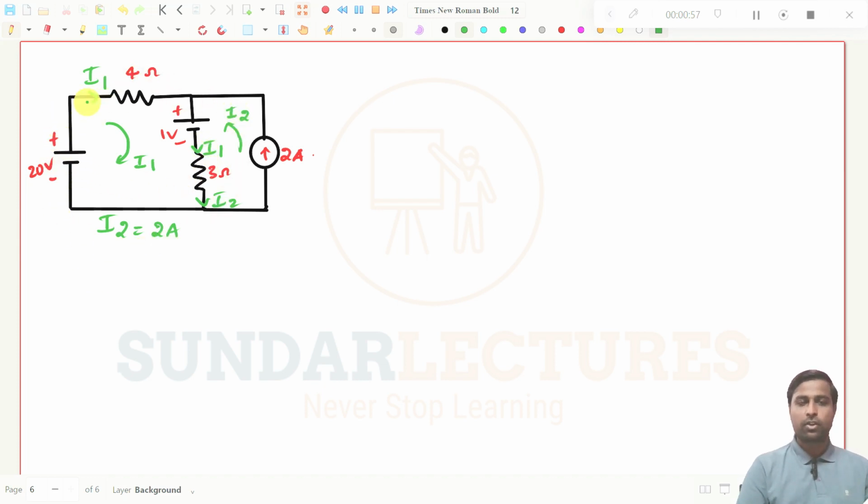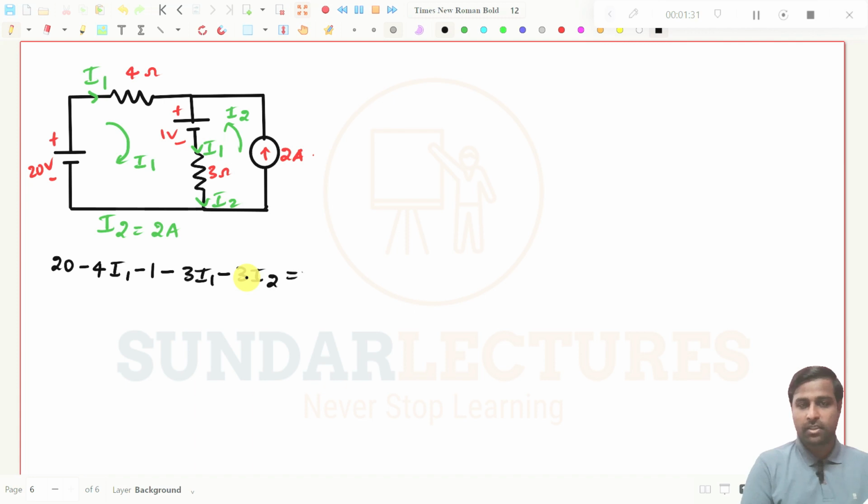Now if I want to solve this problem, I need to write the first loop expression. It will be 20, and going in the same direction, minus 4I1 from plus to minus. In the 1 volt source, it will be minus I1 minus 1 volt, and then going in the same direction, minus 3 into I1, and again the current direction is the same as I2, so it will be minus 3 into I2, which is equal to 0.